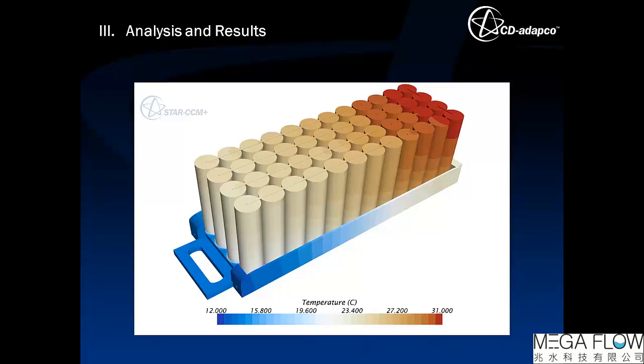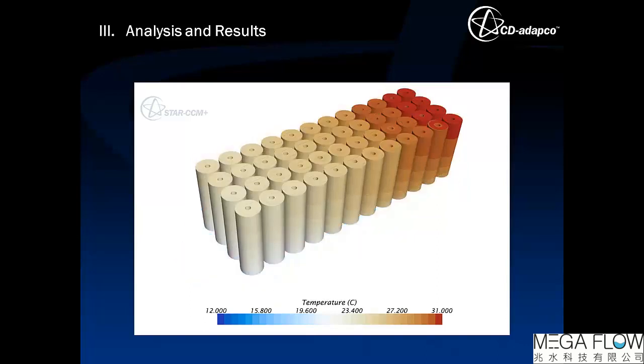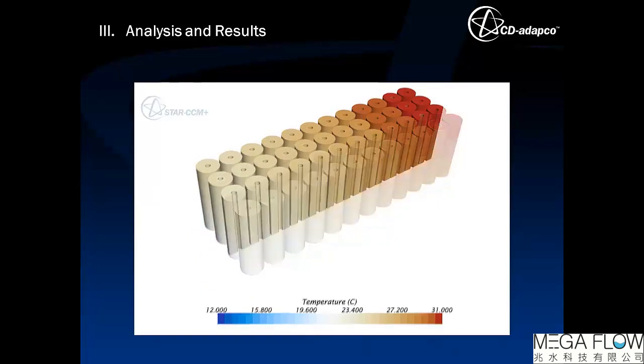Creating our design, we want to ensure that it will present the most homogeneous temperature distribution to ensure the best electrical performance, but also the longest life expectancy for the battery cells. Looking at the jelly rolls themselves, I can notice the rather large temperature difference across all of them. Even looking at the inside of the jelly rolls, we can notice this temperature spread for each of them. So we need to have a bit more investigation on why we have this large temperature difference inside the module.